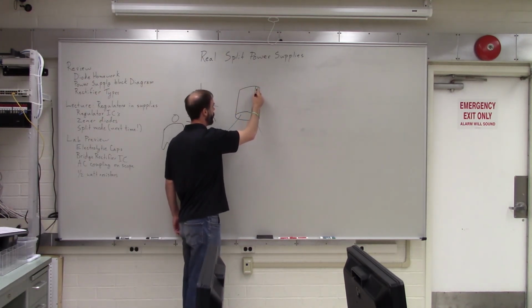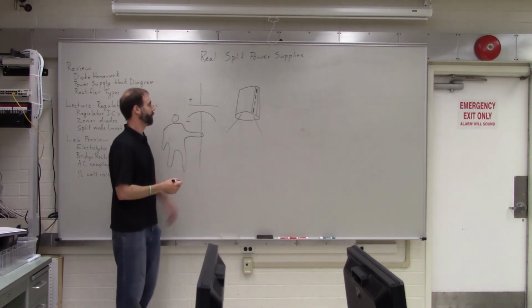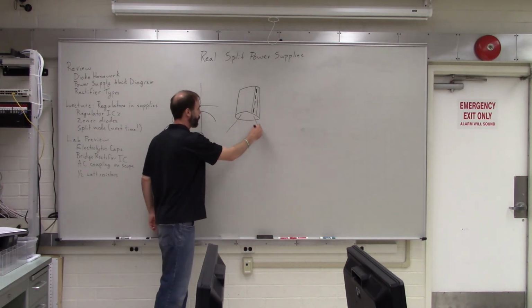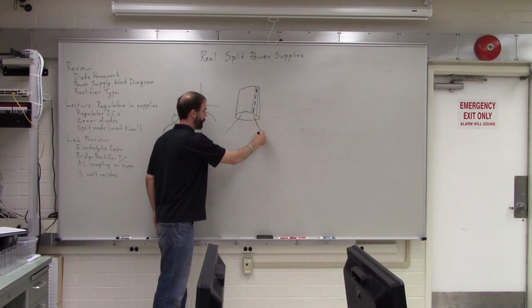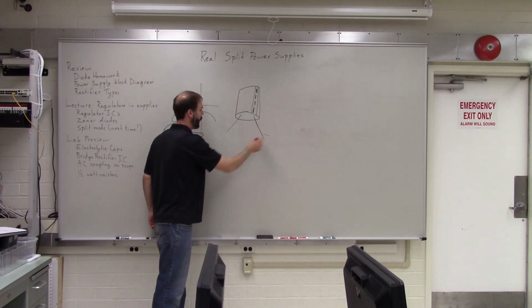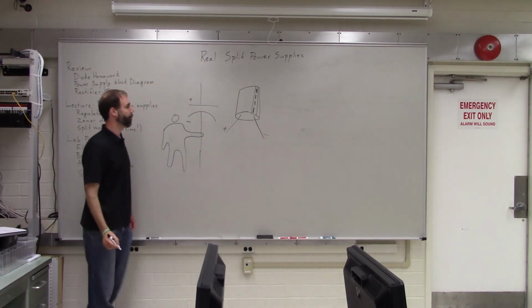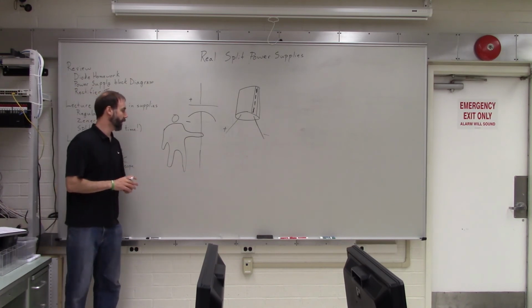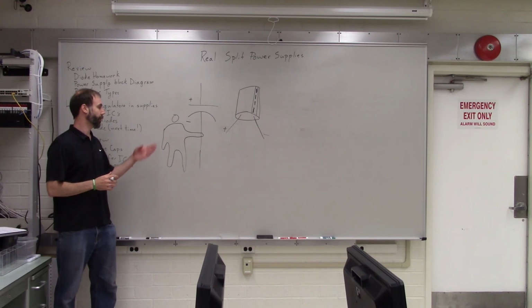And they're not sideways, they're lengthwise with the capacitor. So they can look like lines, or like a dotted line, but they're meant to represent negative signs. So the leg that's closer to the strip with the negative signs is the negative leg. The other one is the positive leg. Okay. So make sure that you watch out for this, and when you have an electrolytic capacitor, you plug it in the right way there.